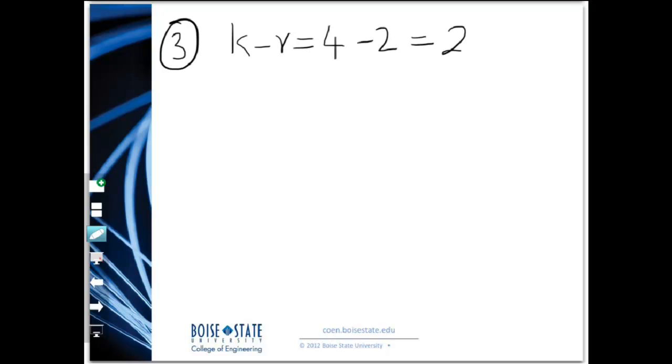All right. So step 3. The number of pi groups we expect would be K minus R. So 4 minus 2, so 2. We need to come up with 2 pi groups for this problem. So step 4, we need to pick 2 repeating variables, same as the number of primary dimensions in the problem, which was 2, L and T, right?